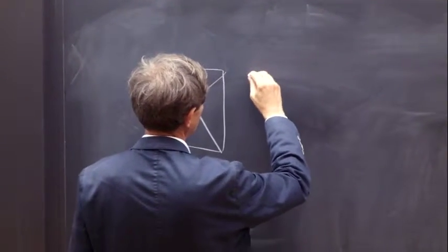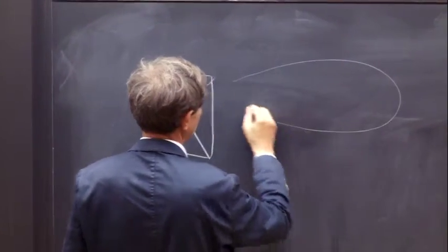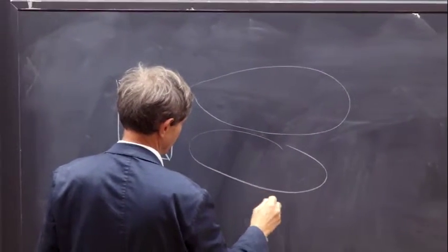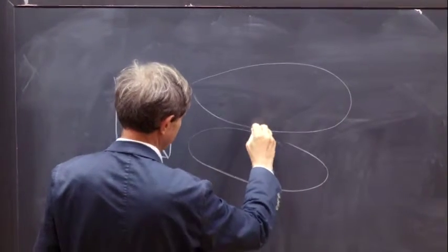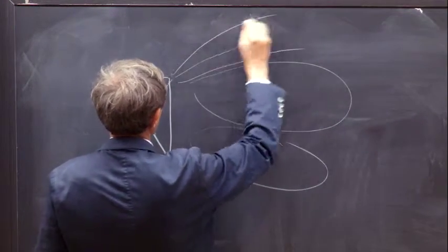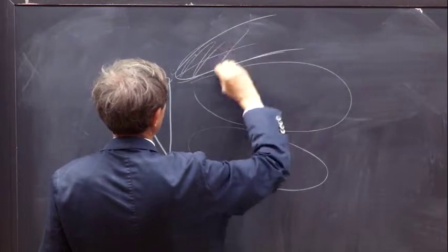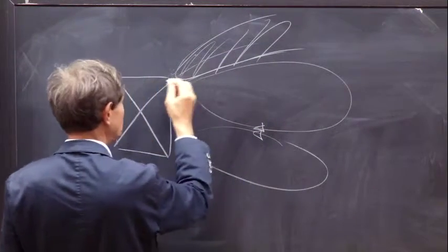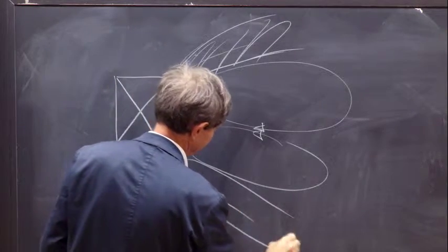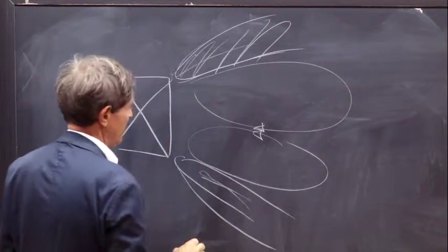What happens is that you produce in this region a recirculation of hot gases. So these hot gases will ignite the flame. You don't want the flame to sit on the swirler, on the injector, but it's not far.